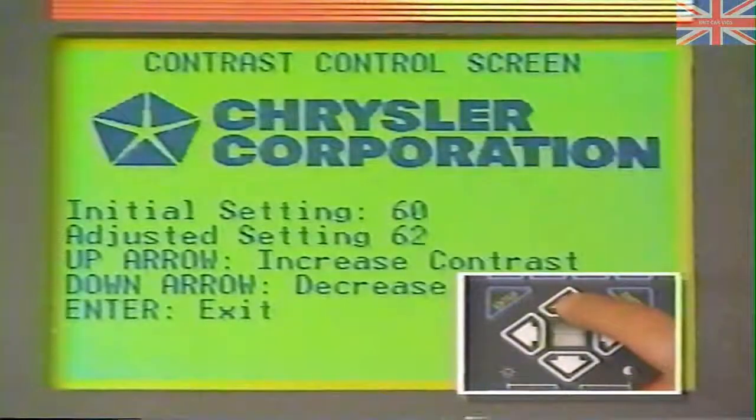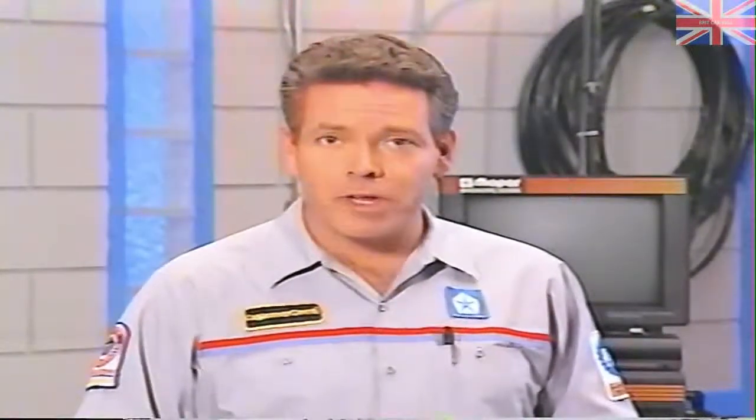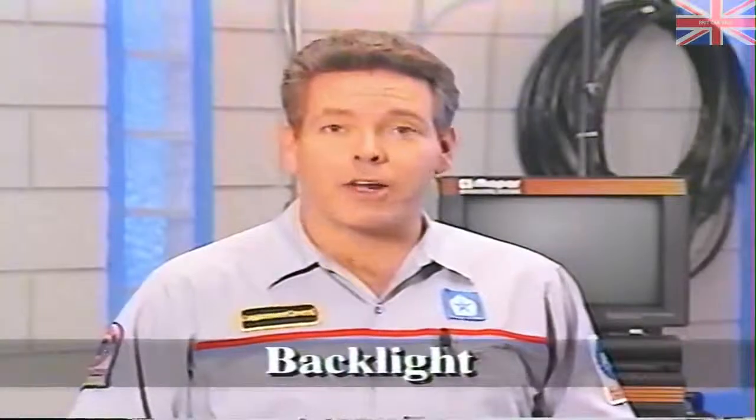However, this set range may not be appropriate for certain conditions, such as very warm or very cold ambient temperatures. So when contrast control is adjusted at power up, the first screen the DRB3 will show is the contrast control adjustment screen. You'll need to adjust the screen as necessary for your conditions. In addition, when the DRB3 gets hotter, the screen gets lighter. This can make the DRB3 difficult to read. But now the automatic contrast feature adjusts the contrast at set intervals to prevent the screen from getting too light. In the January 1994 MasterTech, we also mentioned a backlight feature.